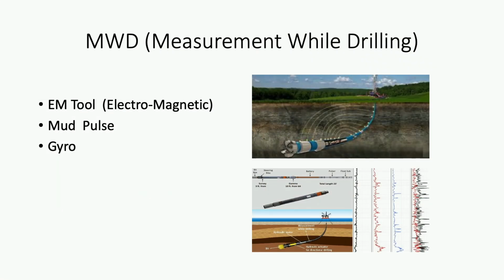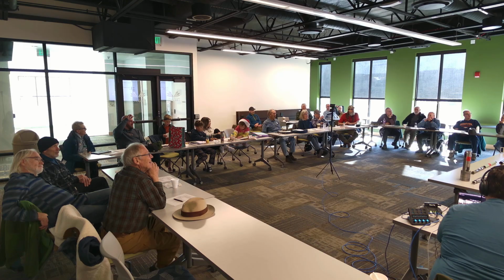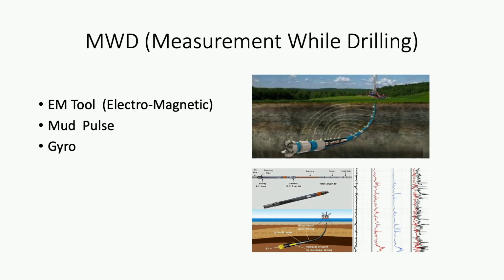Will it? If the mud's not flowing properly or, nope, the transducer itself will just only tell us pressure. So we do have, I'll get into that a little bit later, a system where we monitor everything on the rig. So I'll get to that after this. And then we utilize our gyro. Like I was telling you before, if there's a case that we can't use mud pulse or we can't use EM, then we go to gyro.